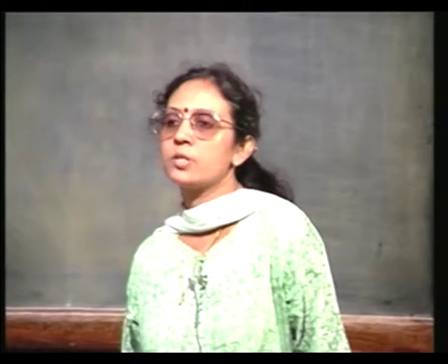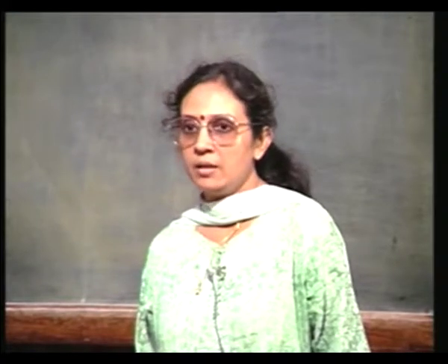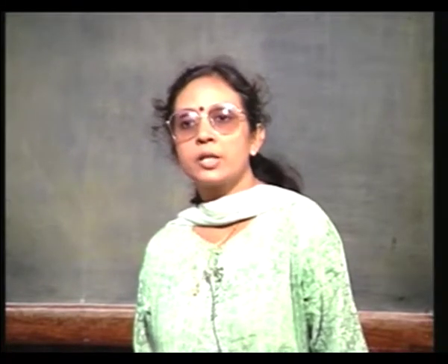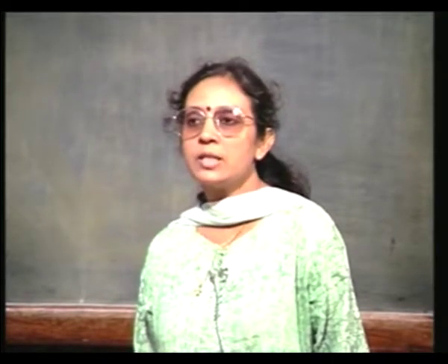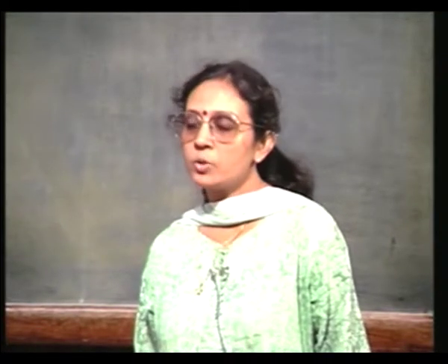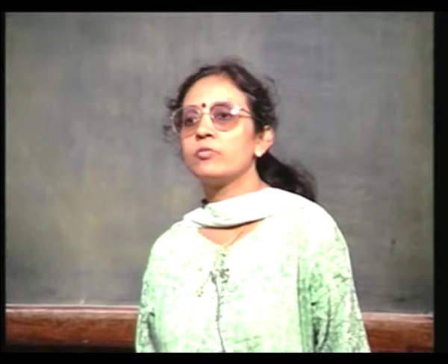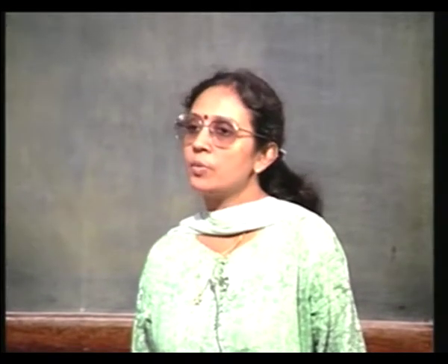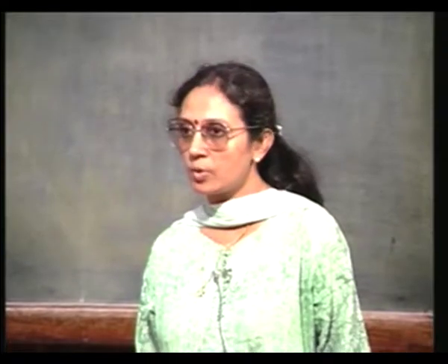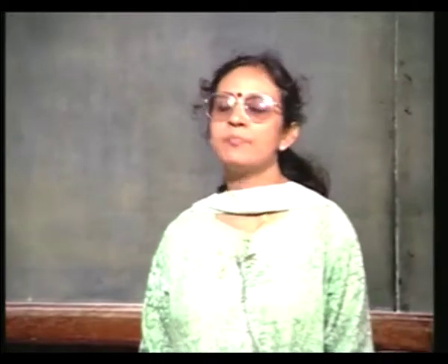Take for example, the question of latch up. If I want to prevent latch up, then we could use a retrograde well structure. If we use a retrograde well structure, it is actually coming closer to the bipolar junction transistor technology, because what we are using is the same buried layer, buried N plus layers, which will be used to cut down the resistance of the N wells, as well as it will be used to cut down the collector resistance problem of the bipolar junction transistor.